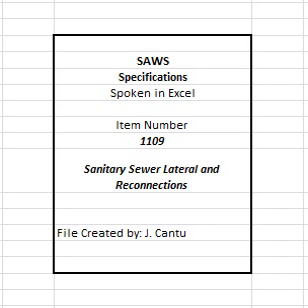6. Installation of new service laterals. A. Install laterals on sanitary sewer main for each service connection. B. Provide the length of stub indicated in the contract documents. C. Install plug or cap on the upstream end of the service stub, as needed. D. Test each lateral connection before backfilling.